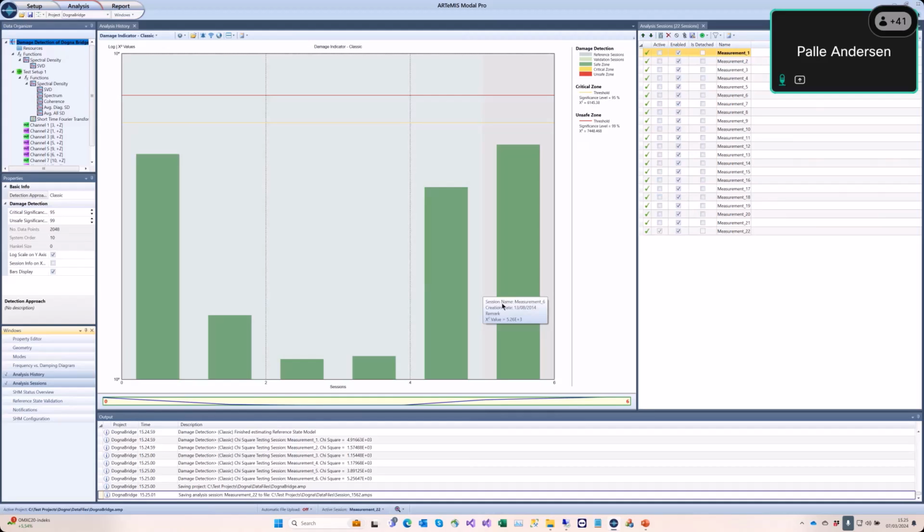And once we have done that, with the reference state where everything is okay, we can then use it to compute 2 thresholds. So we have to calculate the mean value and the standard deviation, and then we multiply the standard deviation with some kind of significance level, and then we get a 95% confidence level threshold here, and one for 99% over here. So we have these 2 that serve as our thresholds. If we are below those, everything is good.